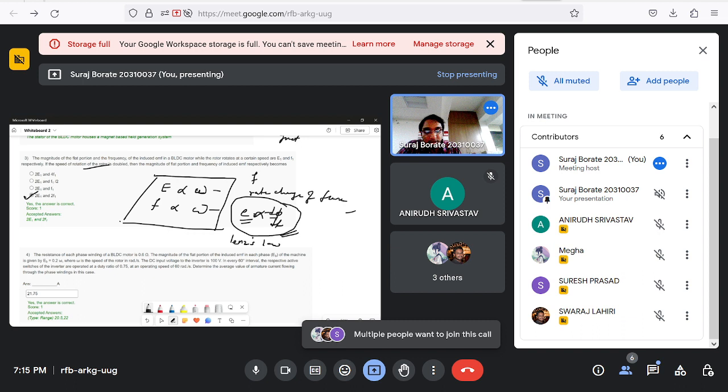Yes, sir. Ideally, at least one of the switches will be off. Since there are only four switches remaining, it essentially is an H bridge. If all the six were doing something in some other fashion, then we would not be able to apply this formula, but since only four switches are being currently used, it is actually resembling this. So one of the legs is inactive.